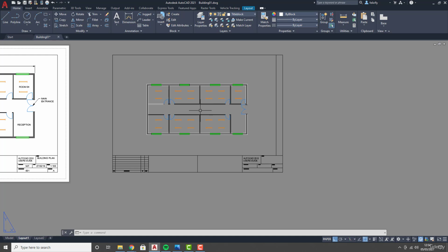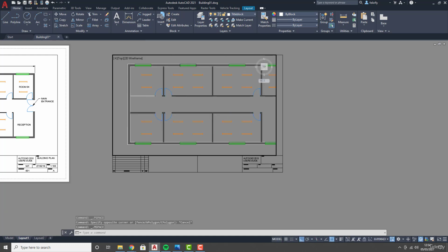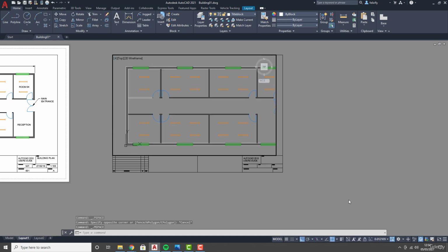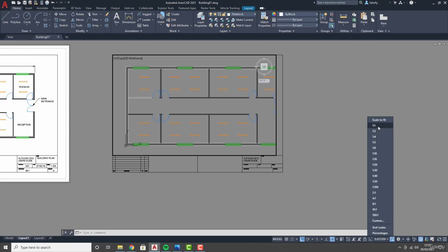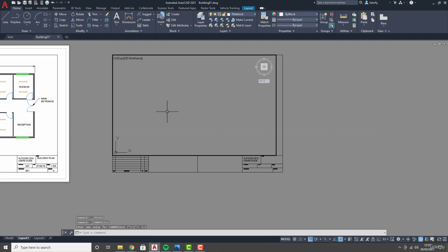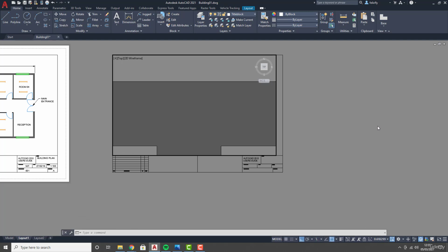And we can do that easy in CAD. So we can double click in our window, and instead of using the zoom command, if we look down here, we have the standard scales kind of set up. So if we wanted to show its actual size, that would be 1 to 1. And if I just pan it a bit so we can actually see it, let me do it on something. So if I set this at 1 to 1, that is actual size.